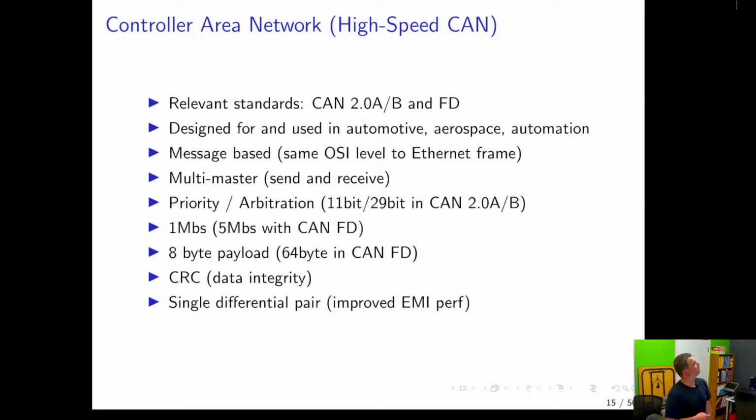It's message based, so everybody on the bus sees all the traffic, and it's designed so that sensors just keep sending their data, their status, constantly. You don't have to query anything. You can query, but the goal is a message-based system. It's multi-master, so every node can send or receive whenever it feels like it, versus, let's say, SPI, which has a single master that has to give time to each node to talk.